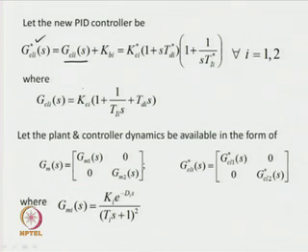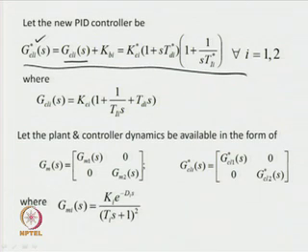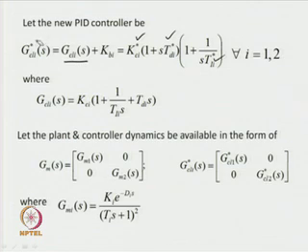Now, the form of the new PID controller is given over here, which is a series PID controller with proportional gain KCi*, derivative time constant TDi* and integral time constant TIi*. So, for all values of i 1 to 2, we shall get 2 new PID controllers for the 2 input 2 output process.